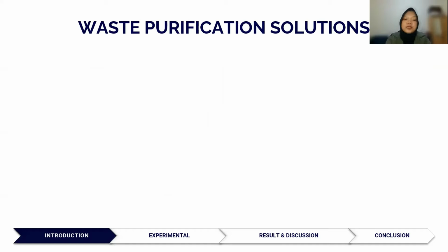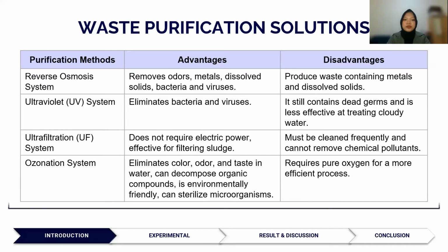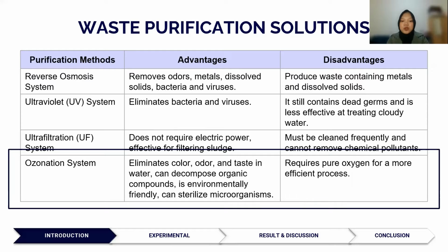Well, to process the wastewater, here are some solutions which are offered. And I took the ozonation system to purify the wastewater. The advantages of this system are that it can eliminate color, odor, and taste in water, can decompose organic compounds, is environmentally friendly, and can also sterilize microorganisms. While the disadvantage of the system is that it requires pure oxygen for a more efficient process.